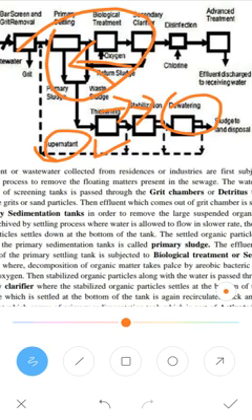The effluent, that is wastewater, which comes out from the secondary clarifier is fed into the disinfection tank, where chlorine is added to the wastewater to kill the germs and pathogenic bacteria present in the water. Then any remaining germs in the water which comes out from the disinfection tank are removed in the final or advanced tertiary treatment process, where the water can be directly discharged to nearby water resources.